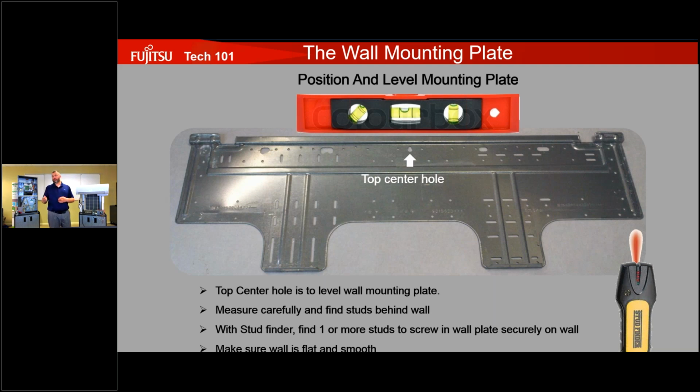So taking a look at the plate itself, right down here, this is where the indoor unit clips into this bracket, and they're on both sides. Not really too sure if you could see it. There's a little hole in the black bracket that the unit clips down into. When you're going to take this unit off the wall for service issues or what have you, one of the stress points that you're going to have is going to be right here at the bottom.